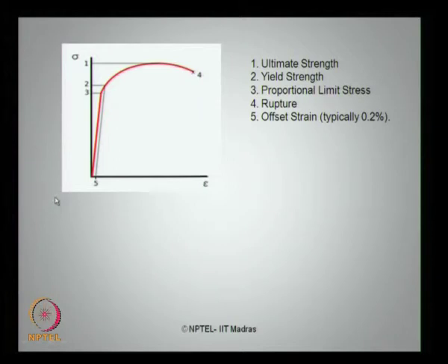There is a very interesting figure, a stress strain curve, which all of us as engineering students know. Let us quickly understand its importance in the selection of material for the marine environment. It is a classical stress strain curve for a ductile material which I am showing here. There are different points which I am indicating here, 1, 2, 3 and 4, where 1 stands for the ultimate strength of the member, an index shown on the stress axis.